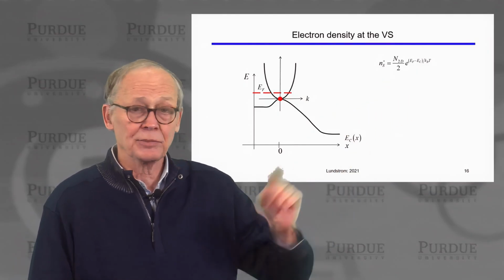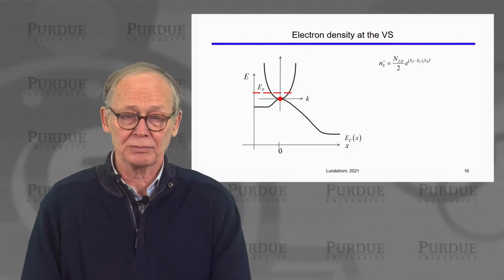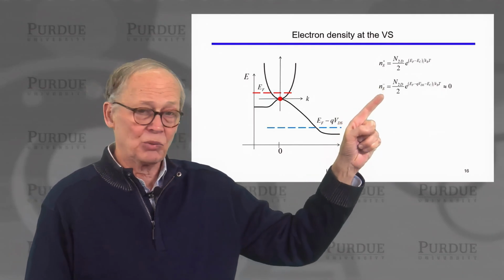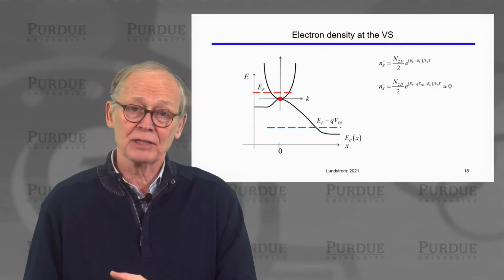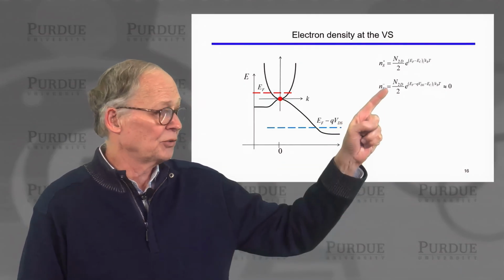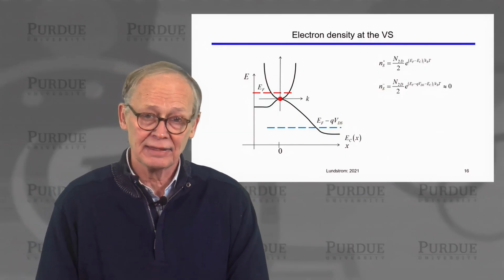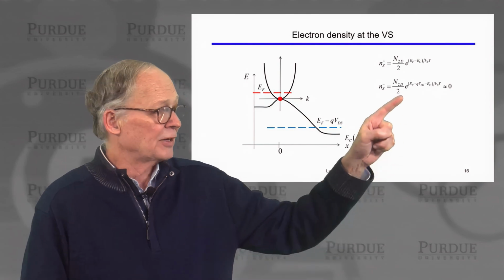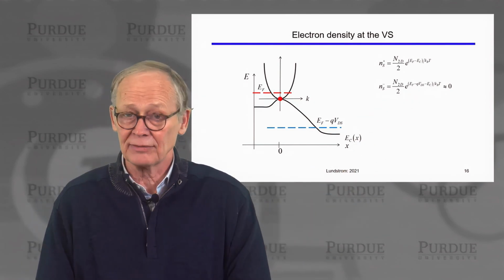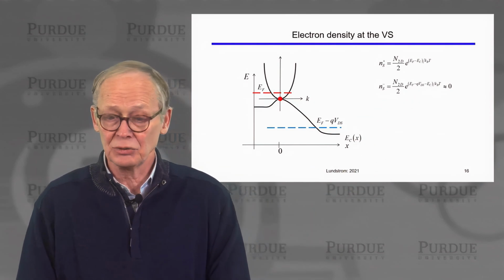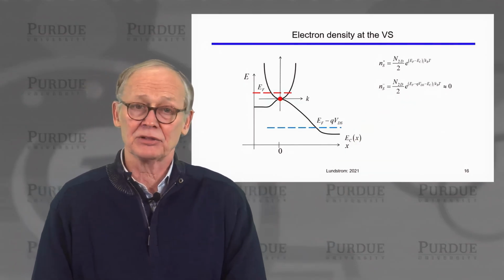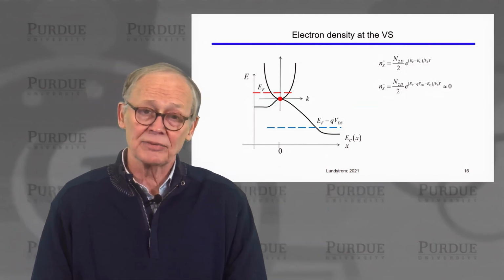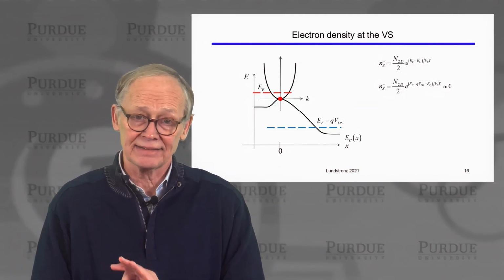And the Fermi level is the Fermi level from the source, because that's where the positive velocity electrons came from. Now, if I ask, what is the density of electrons per square centimeter with negative velocities? Well, only half of the states have negative velocities, so I divide the effective density of states by 2, and then I occupy those states according to the Fermi level of the drain, or contact 2, which is lower by an amount that's determined by VDS. Well, VDS is so large that the number of those negative velocity states is essentially 0.